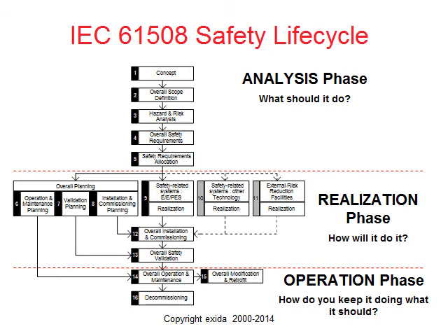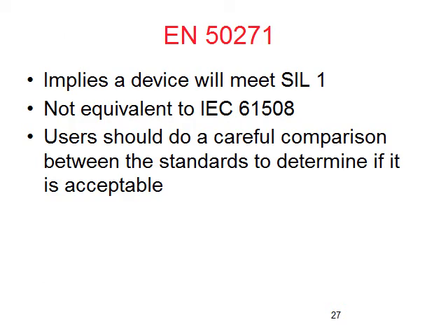And then finally, to go back to this, IEC 61511, which is the thing referenced by OSHA. They reference S84, which is the modified IEC 61511, or it's the standard pointed to by the Seveso directive, or it's the standard that the Australian gas authorities are going to look at before they allow you to put gas to your plant.